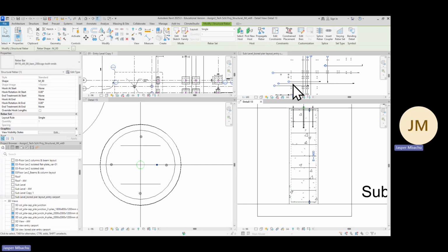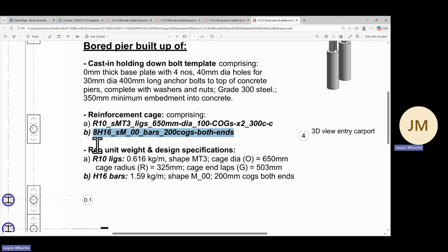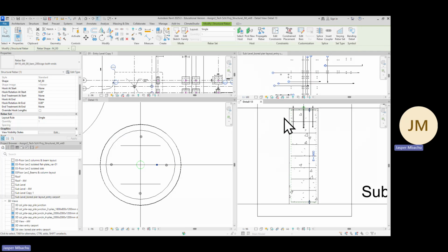Okay. So when you've done that, and the rebar cover is showing the name that you want, then we were told that we need to place eight of those. So there are 8 numbers of those. So while this bar is selected, we will come here. Is it maximum or fixed number? It is fixed number. Click on the fixed number and then we type 8 here. And then there will be 8 of those instances.